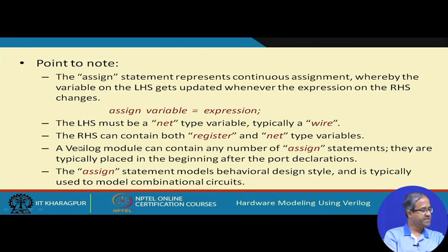Now, as the previous example shows, a module can contain any number of assign statements, and as a matter of convention, these assign statements are placed towards the beginning of the code right after the declaration of the ports.